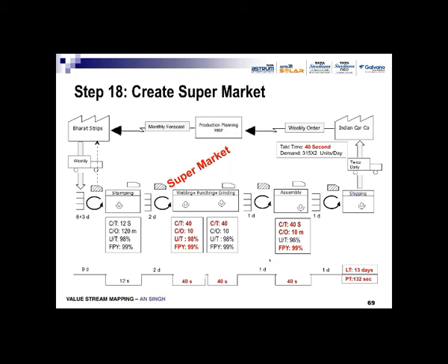Between the welding, punching and grinding there is no inventory involved, and all operations are made at one place, and the supermarket is created, so that without interruption of production, enough stock is maintained. At the same time, inventory is drastically reduced. As long as the supermarket is full, the previous process need not operate. Once it is empty, then they have to start refilling.